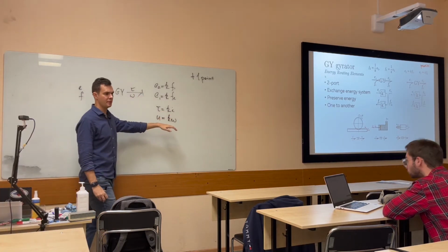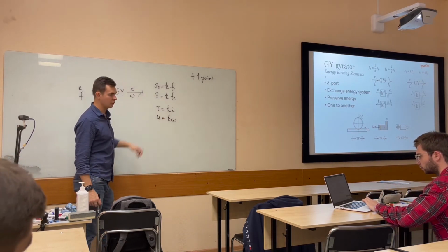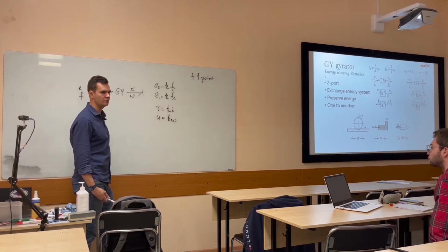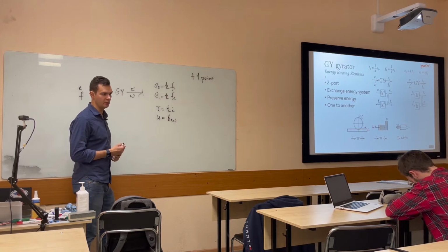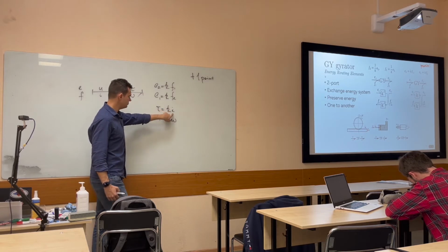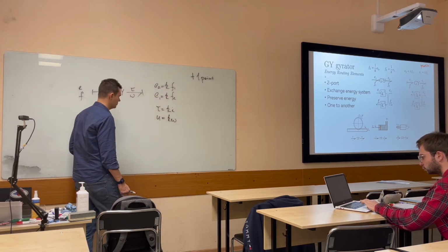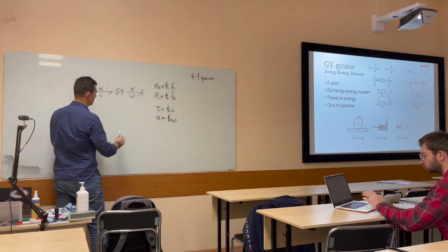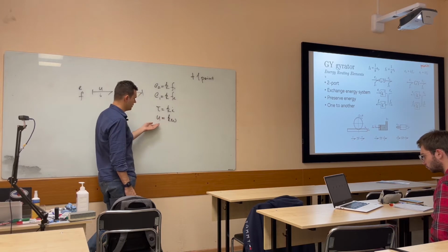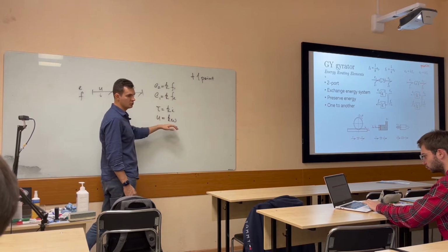And if you know something about, for example, a DC motor, you know that this k is called the mechanical constant, and it's something that you can find in the datasheet of all the motors. So it's the linear characteristic between current and your torque, and here the voltage and angular velocity are also proportional to each other.